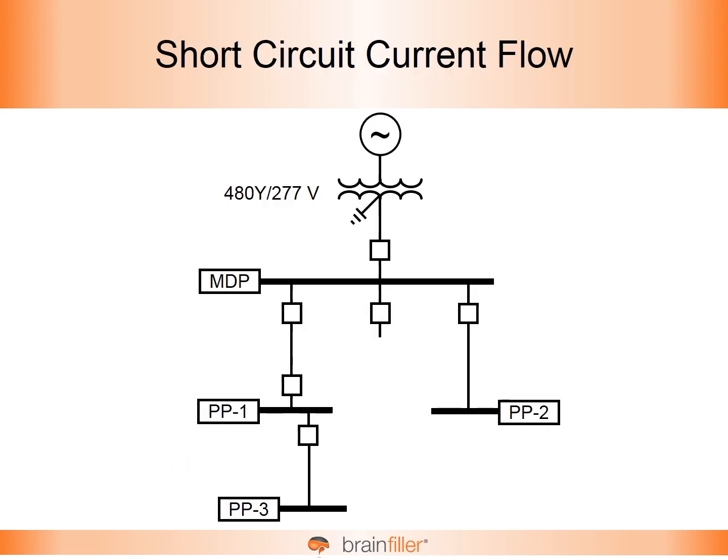In a short circuit study, which is part of what an arc flash study is based upon, a system model is created based on impedances, based on utility data, based on conductor and transformer data, and the calculated short circuit currents are oftentimes going to be listed on a one-line diagram. In general, what normally will happen is the short circuit current tends to be greater closer to the source, and the further away the short circuit occurs, the short circuit current tends to decrease because of the additional impedance between the more remote location and the utility system or the source.